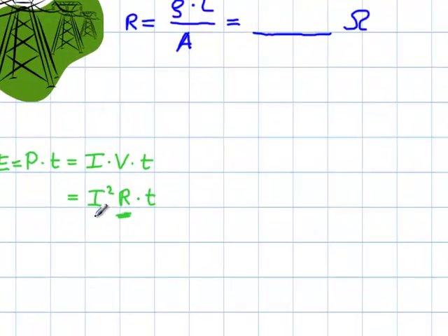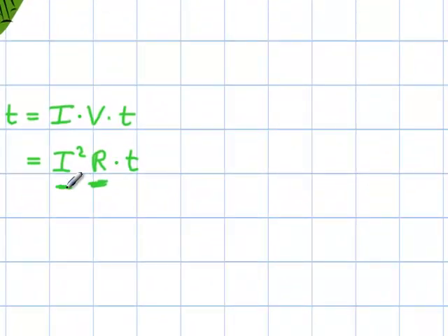And the other one is that the current should be pretty small, and that's why you see such high voltages on the power lines, because that high voltage, after it goes through a transformer from the power plant, the voltage is being stepped up, but the electric current is being stepped down in order to get as little of an electric current running through the wire as possible with, well, a very high voltage at the same time, so that the power loss within the power lines is relatively small. That's just on top of what the problem asked about, but I figured, hey, this is a problem on power lines, so I might as well mention that.